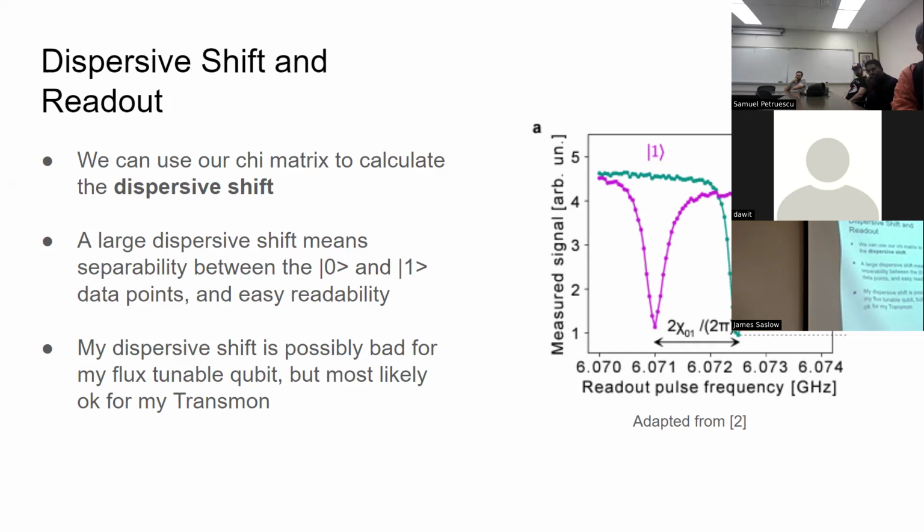Yeah, but that's a very, very important point. Also, to actually extract these signals that you want, you need reflections of your microwave signals. So you want your microwave signal to reflect off the qubit, so that it carries information about the qubit to read out. But I haven't gotten into that part thoroughly yet. That's kind of the future goal.